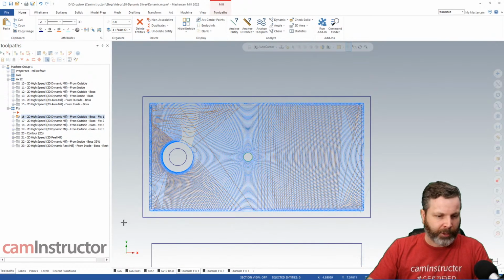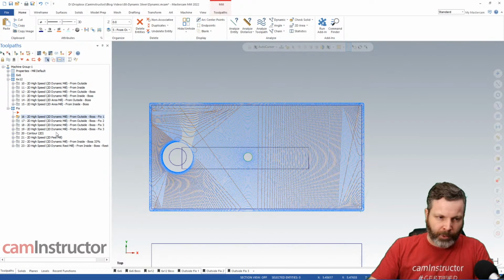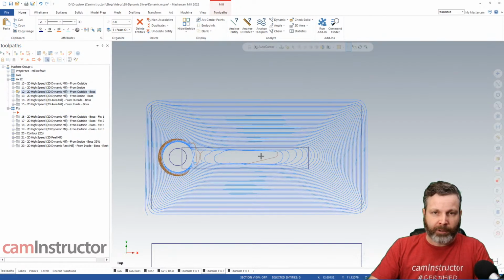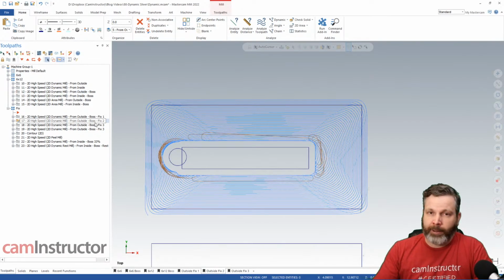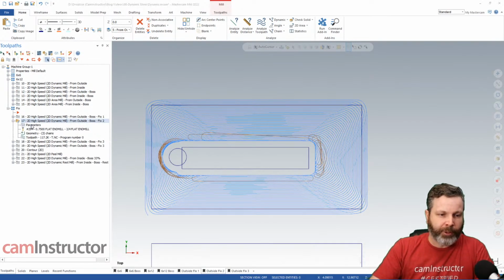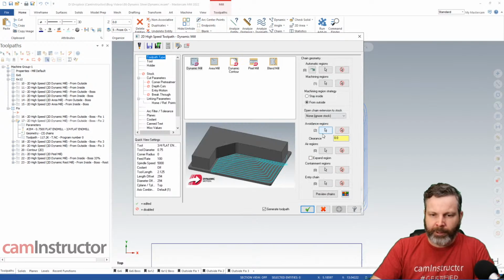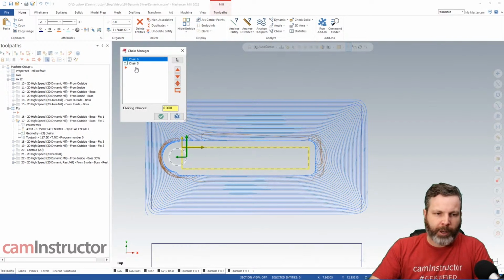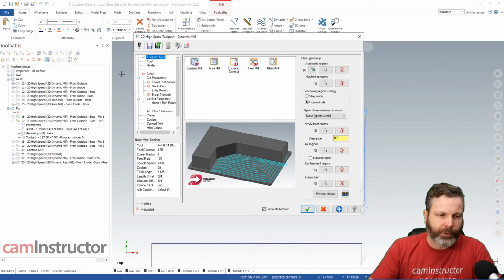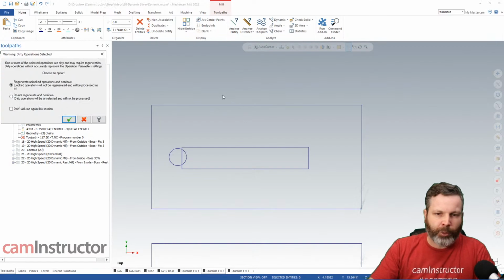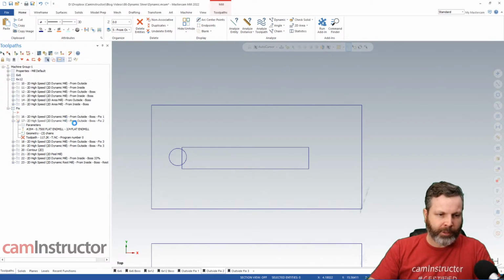What's another option, what we can do here? So we can just avoid cutting this section altogether. So what I've done here is I've drawn, just freehand, a block that basically encompasses where the sliver would happen. I add that to my chaining geometry as an avoidance region. Up in here, it's in my avoidance region. So I'm avoiding the boss, and I'm avoiding this box that I've drawn in to avoid cutting the sliver. So do we avoid cutting that sliver? Hop into a backplot here. Oh, I made some changes there by accident.